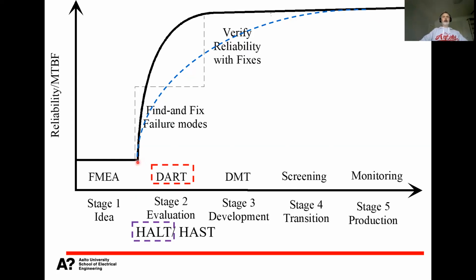Or we have a target coming from the car manufacturer that the MTTF, so the random failures, needs to be less than 0.1 FIT. So 0.1 failures per 1 million operational hours. So that's our reliability target.